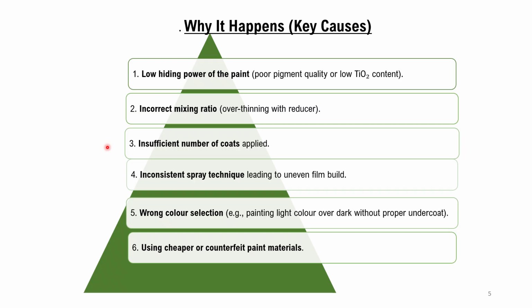Insufficient number of coats applied. Number 4, inconsistent spray technique leading to uneven film build. Wrong color selection, e.g. painting light color over dark without proper undercoat. Using cheaper or counterfeit paint materials.